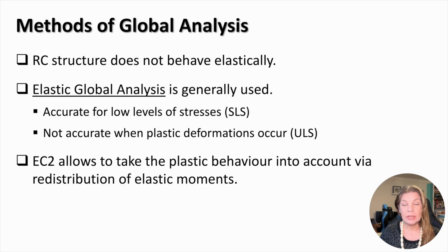We already established that reinforced concrete structures do not behave elastically. However, elastic global analysis is generally used in their design. This approach is accurate for low levels of stresses corresponding with a serviceability limit state. However, it is not accurate when plastic deformations occur, which corresponds to the ultimate limit state.